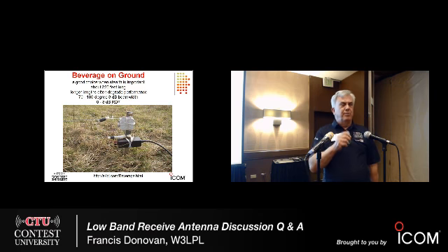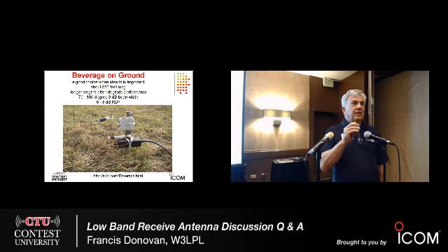You can make small bends. If you deviate from a straight line, it's going to degrade the side lobe performance of the antenna. But if that's the only thing you can do, it's very simple to experiment with. This is a very easy antenna. So if you're not sure, it's not going to take very much time to try it and see if it works well. You're not going to invest but a couple of hours to try to put one of these up and see how it works.